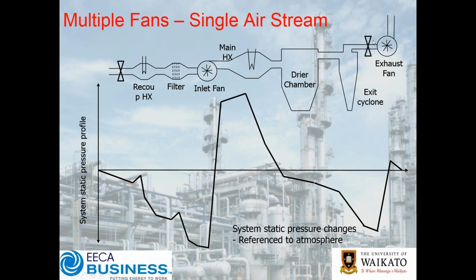But your exhaust fan will be controlling typically to regulate or maintain a certain pressure. You will then have an inlet fan that will be controlling to a certain inlet feed. You then might have a steam control valve which is controlling a temperature of that feed. And then you will have some other reaction feed. In this case you might have a concentrate going to the dryer that will then be regulating the outlet temperature.